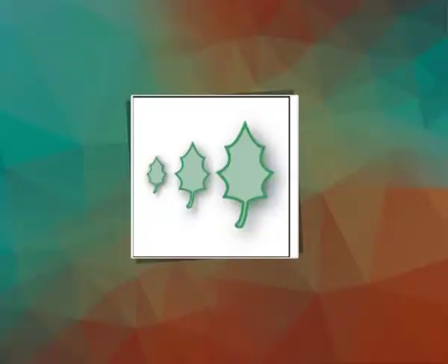Scale objects. Scaling an object enlarges or reduces it horizontally along the x-axis, vertically along the y-axis or both using the scale tool. Objects scale relative to a reference point, which varies depending on the scaling method you choose. You can change the default reference point for most scaling methods, and you can also lock the proportions of an